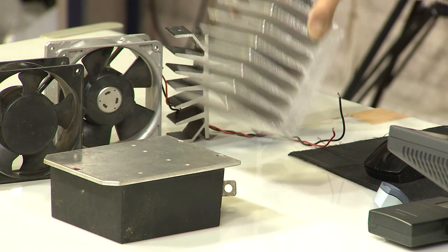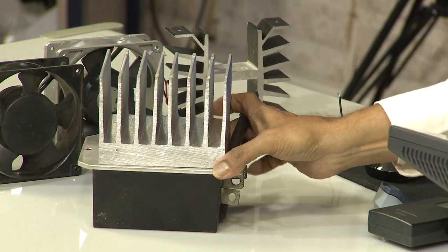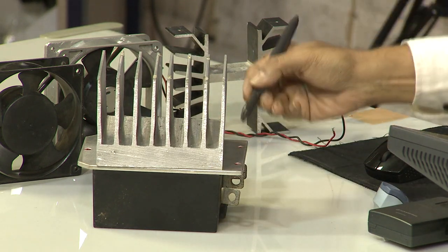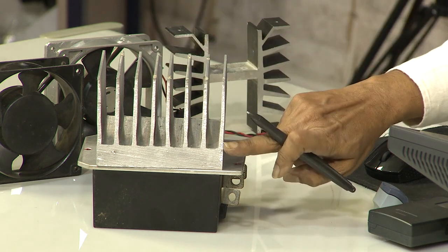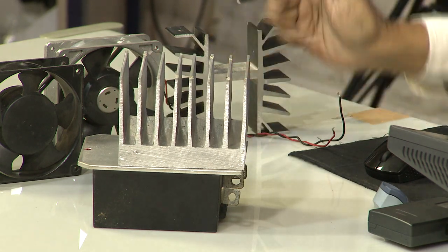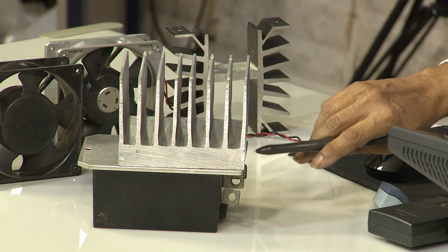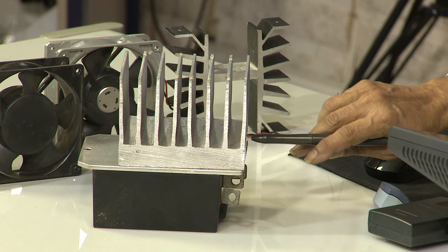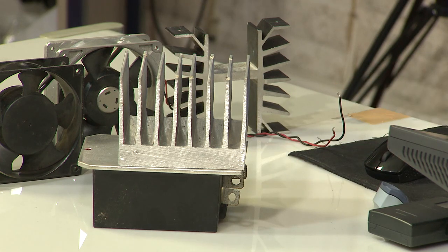Now, having known this data, we place one on top of the other, and then I will find a way of how to clamp this and maybe put a flange or take the next higher size. Imagine this can be brought here, I can take the next higher size, match and drill holes, and put another plate which can distribute the load here, and then either tap this whole thing and insert what are called helicoil inserts.